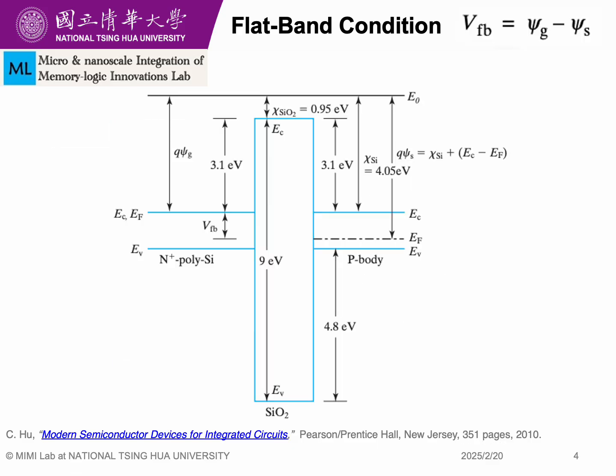Yeah, so when we study this MOS capacitor, it's always good or convenient to first understand the energy band diagram for a special condition called the flat band voltage. So what exactly is this flat band voltage? This is something that you can see here. All these bands are flat, so there is no curve or no bending over here.